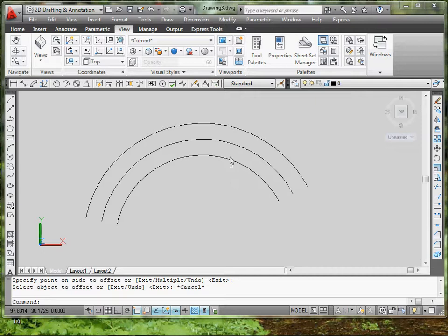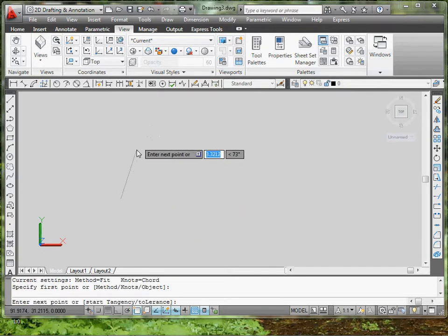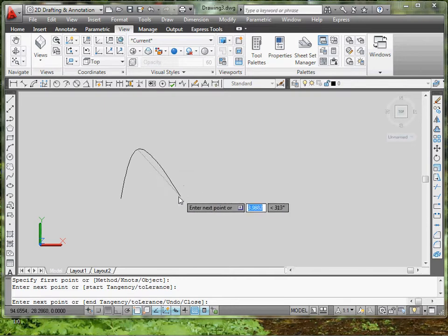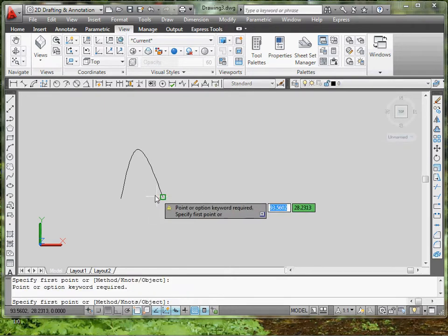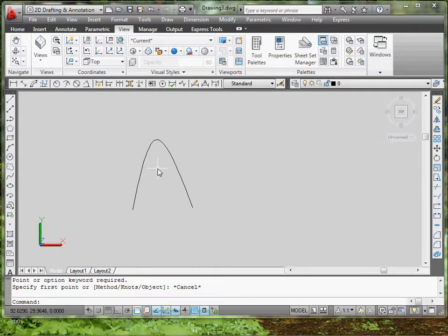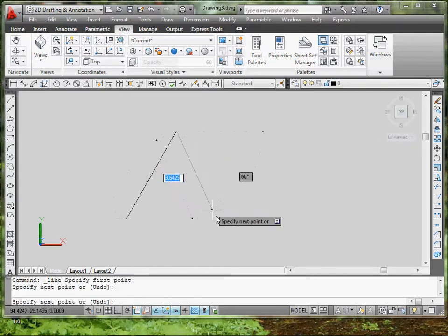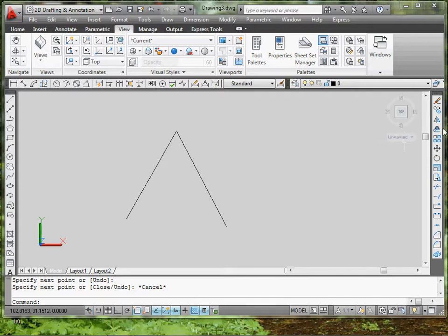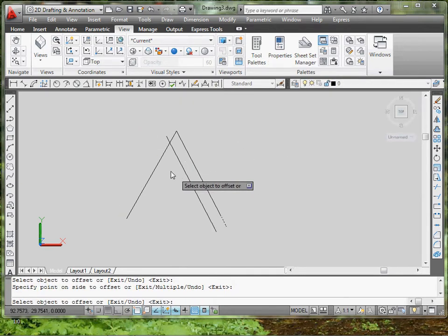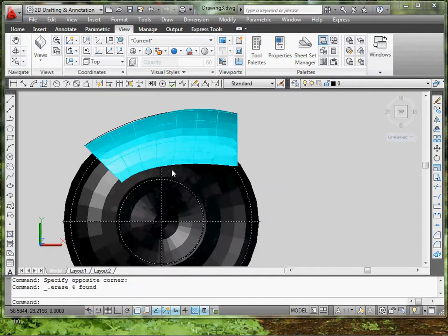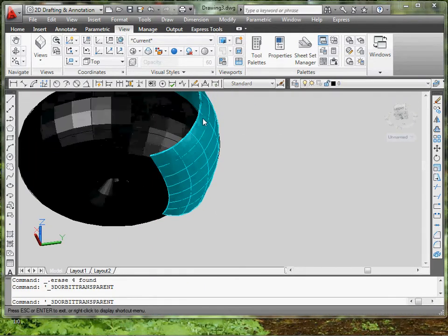Anybody understand? No? Alright, I do a spline. That could help. No, actually a triangle. Alright, so if I thicken this, it would actually thicken this way. Now you might be wondering why it won't go inside. Because if it went inside, it just overlapped right here by the X, and that won't let you do it. So just keep that in mind. Anyways, I have an actual thickened fender.